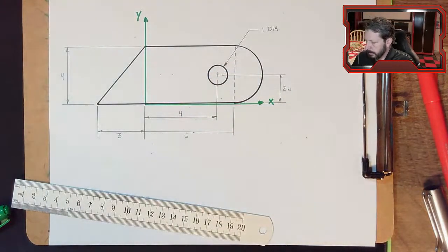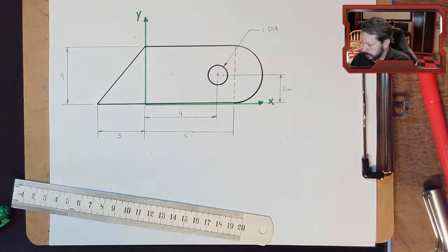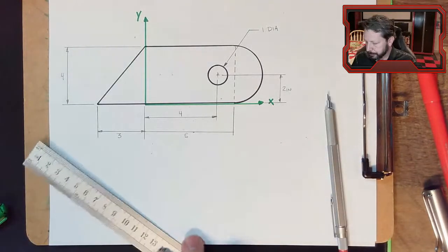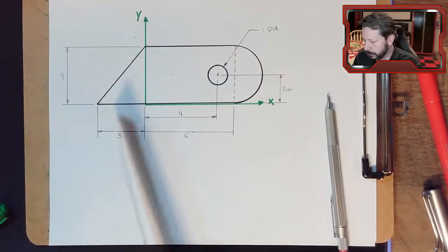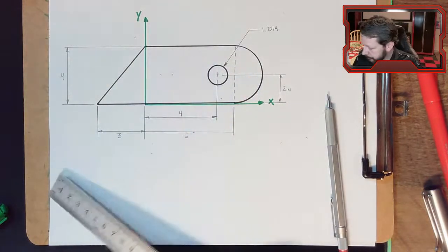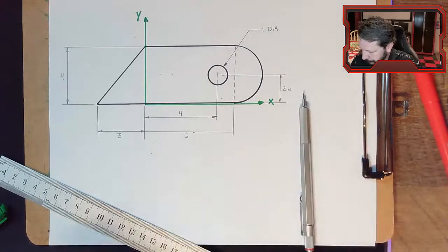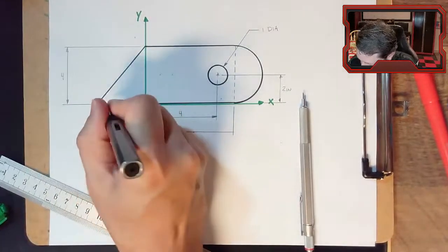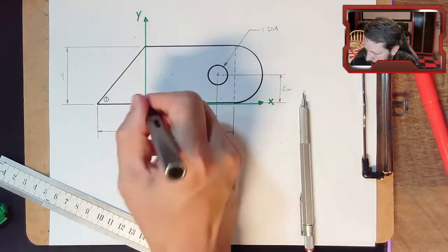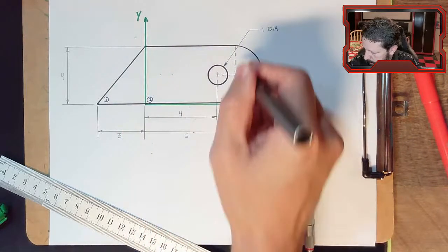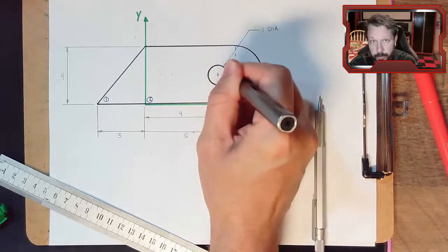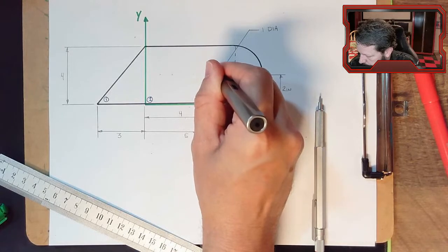All right. For now, I think we've got everything dimensioned. If we need some more, we'll add them when we need them. So what I normally do next, if I'm trying to calculate the centroid of this composite shape, is identify the parts. I have a part that's a triangle here, which I'll call part 1. The rectangle here is part 2. The semicircle on the end is part 3. And the hole in the middle I'll call part 4.